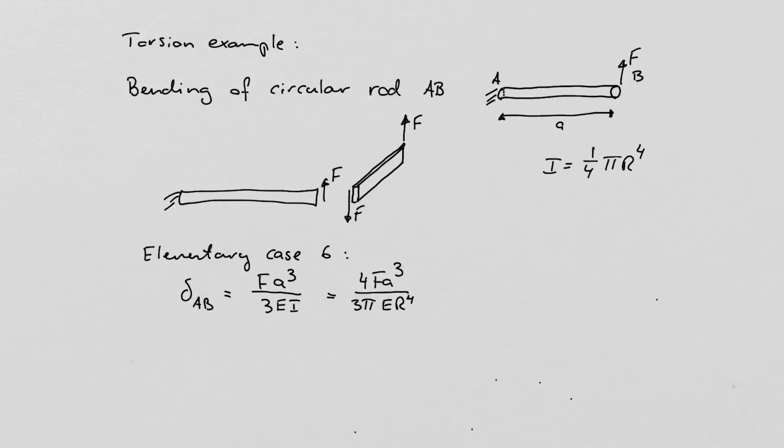So when we do equilibrium here for our handle, we see that in order to maintain equilibrium of our handle, then we need a bending moment that actually goes like this. That will create equilibrium of our force F acting at point C if it has the magnitude F times B, right? The B is the length of the handle. The force is F. So to have equilibrium, we will have to have a bending moment in point B of the magnitude F times B.